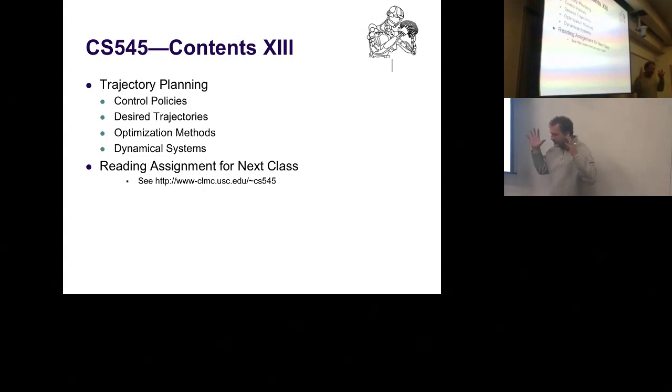Planning, in some sense, comes after you have a control system going. Many people treat planning as largely independent from the robot itself, which is not entirely true. For kinematics, for instance, you cannot violate the workspace of the robot. So either you stay inside or you can reach something or do something. But there are also people who would like to think about planning which includes the controller as well. Some control algorithms, for instance, look into automatically setting PD gains while they're planning a particular movement. Or some people think about whether we could actually plan contacts in a particular way.